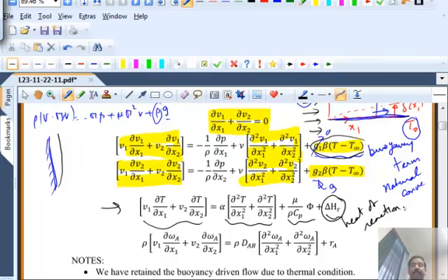And the next equation is the same thing for mass balance. So you have a convective mass transfer on the left-hand side, diffusive mass transfer, and R_A would be the reaction term. That makes the species A either appear or disappear. If A is a product, then it will be a source term. If A is a reactant, it will be a sink term with a negative sign in front of it. So that is the complete transport equations that couples fluid mechanics, heat transfer, and mass transfer with possibly a chemical reaction.